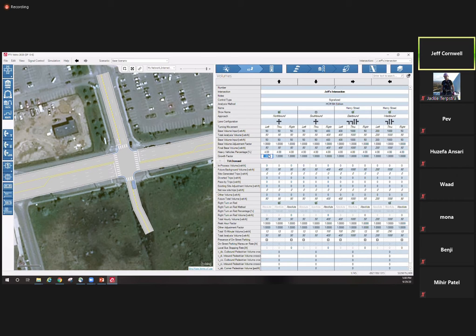Heavy vehicles are important. You'll see right turn on red. So by default, right turns on red are usually allowed, but if you wanted to, you could change that. Unlike Synchro, V-Star is a little different. It actually has where you can add the right turn on red method. So this would either be an absolute number or a percentage. In some cases I might ask you to fill these in, but if you don't know, then you probably want to just leave this blank.